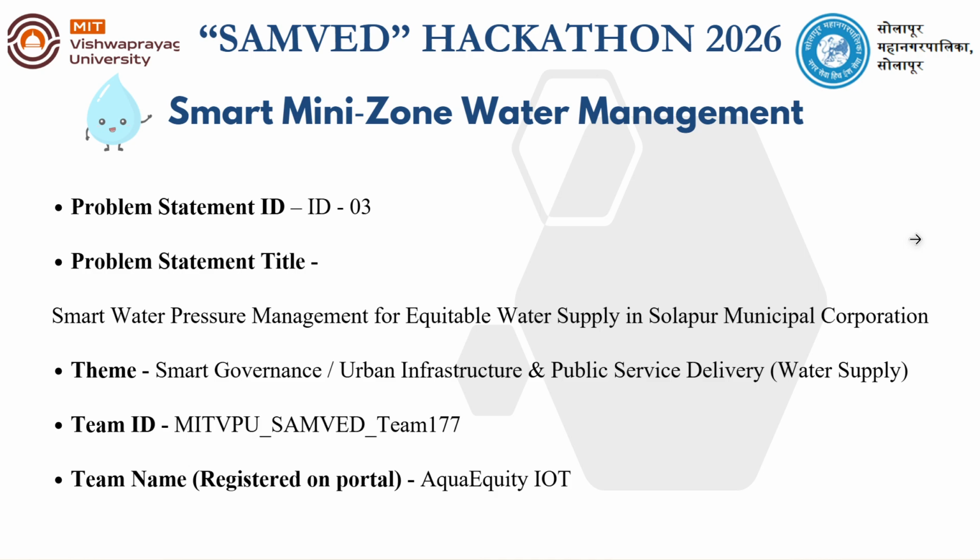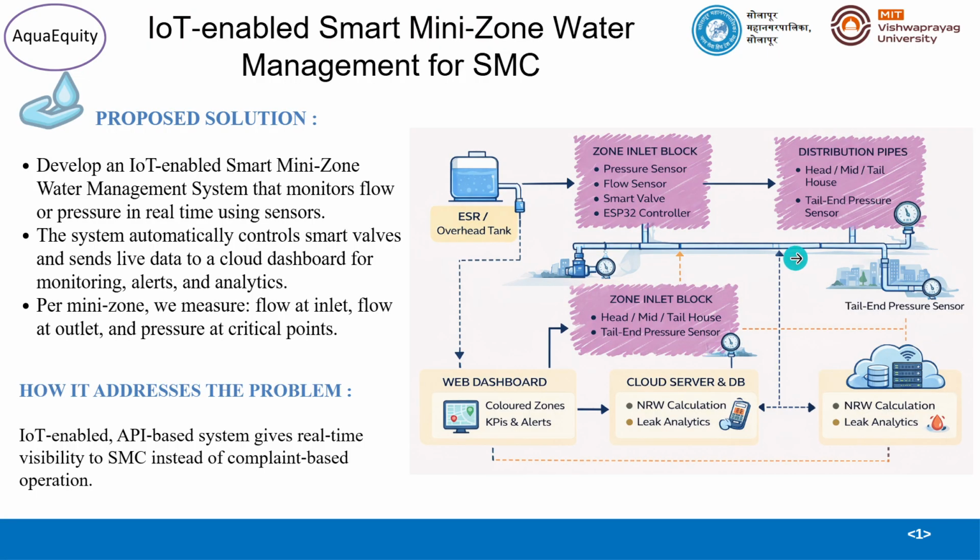Our problem statement title is smart water pressure management for equitable water supply in the Solapur Municipal Corporation. The proposed solution is that we are going to develop an IoT-enabled smart mini zone water management system, monitoring the flow and the pressure in real time using multiple sensors. We are making it for the mini zone, to get the inlet and outlet, and to see how the pressure is going to be handled.